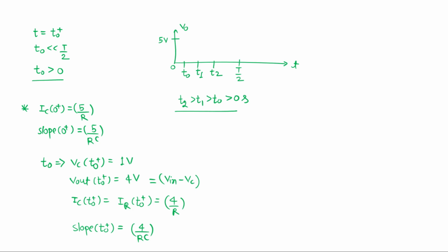It means the capacitor voltage slope is reducing every instant of time. If I plot the capacitor voltage, it has an initial faster slope that we have already seen. After that, a little lesser slope, then lesser slope, again lesser slope. So overall, my capacitor is following some exponential nature. With a continuous curve, it is like this. This is my capacitor voltage.